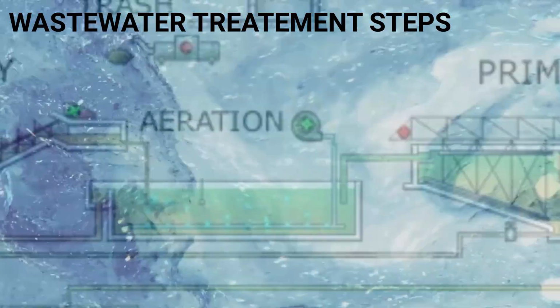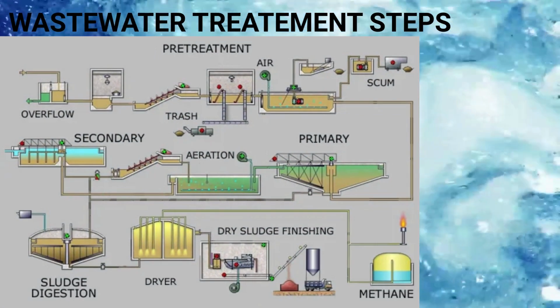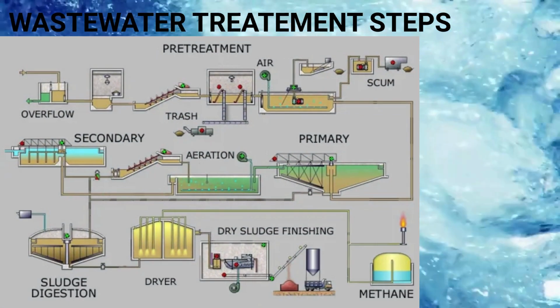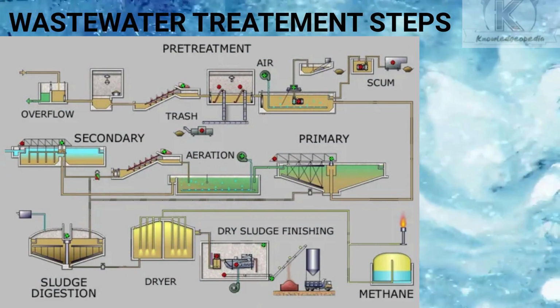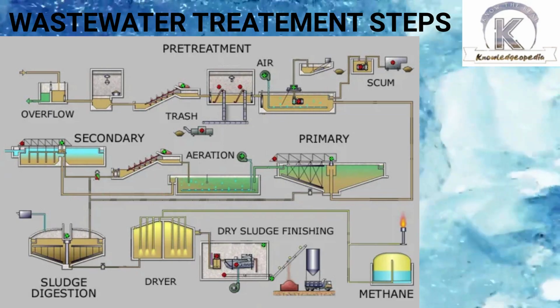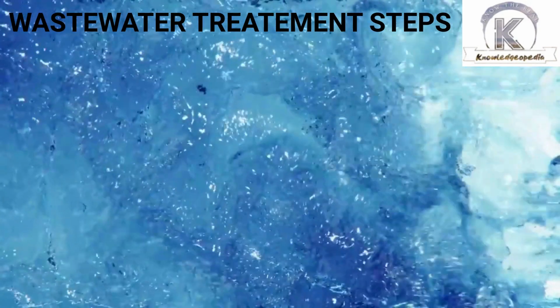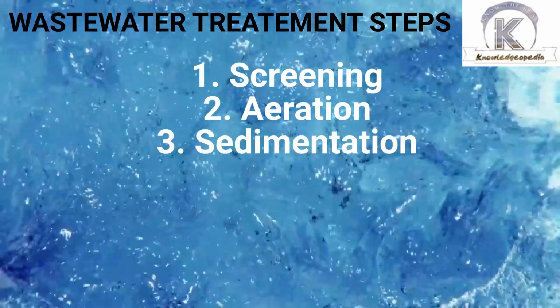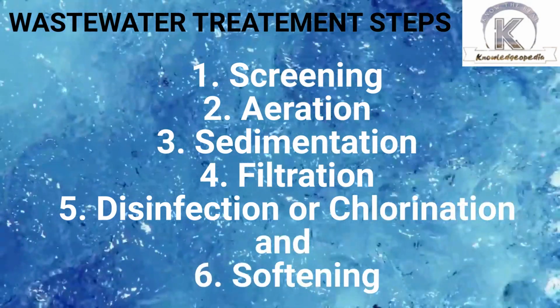My name is Kuntal Ganguly, and you are with me to discuss the basic steps to convert wastewater to drinking water within a very short time. There are mainly 6 major steps during the entire process we are going to discuss, which are screening, aeration, sedimentation, filtration, disinfection or chlorination, and softening.